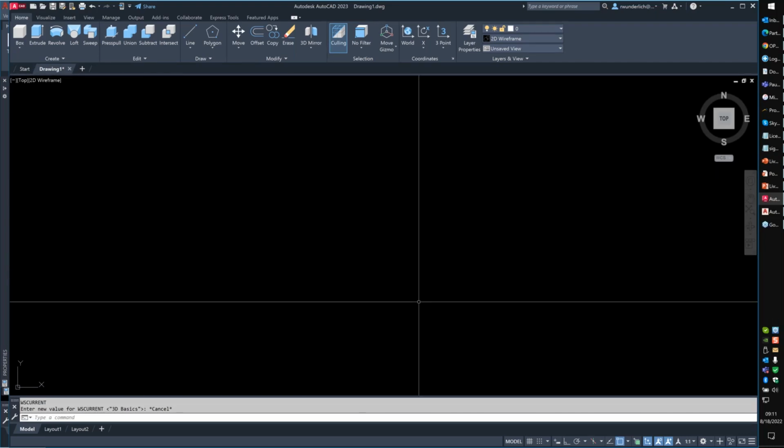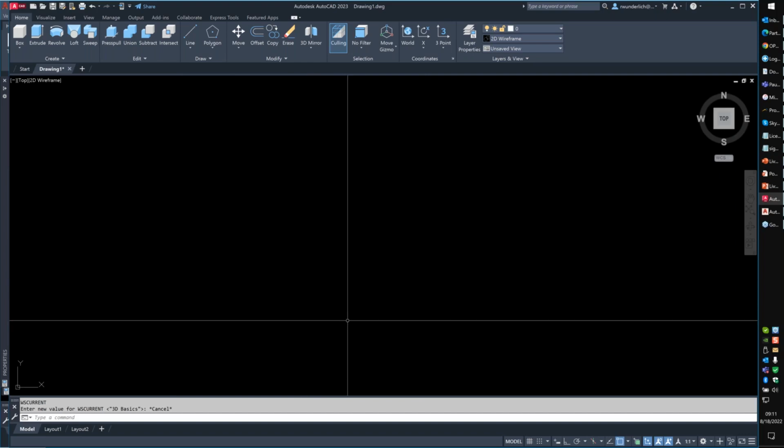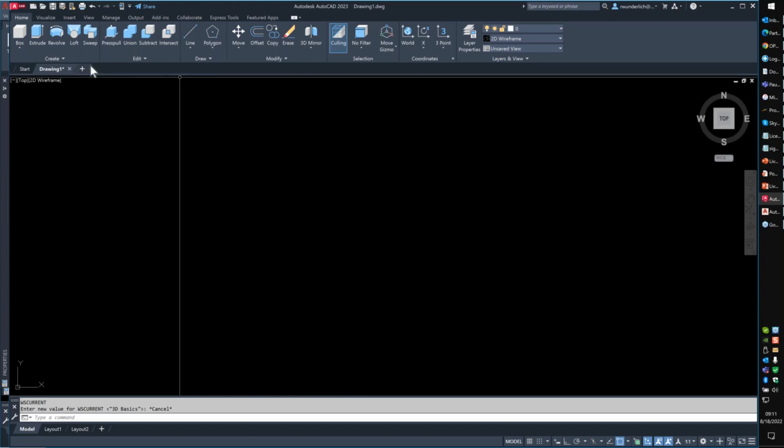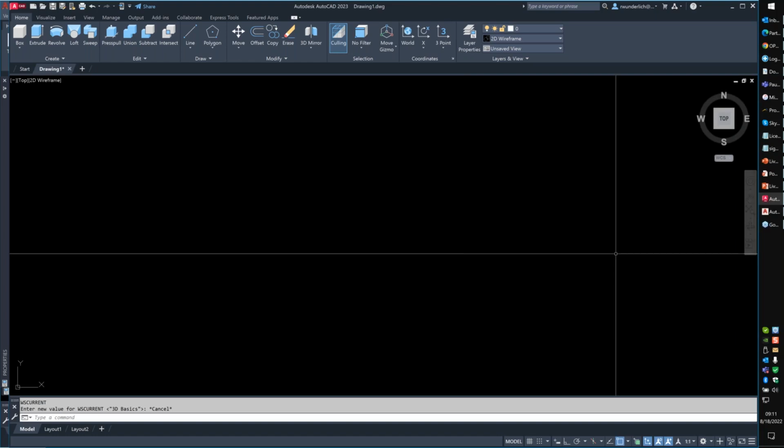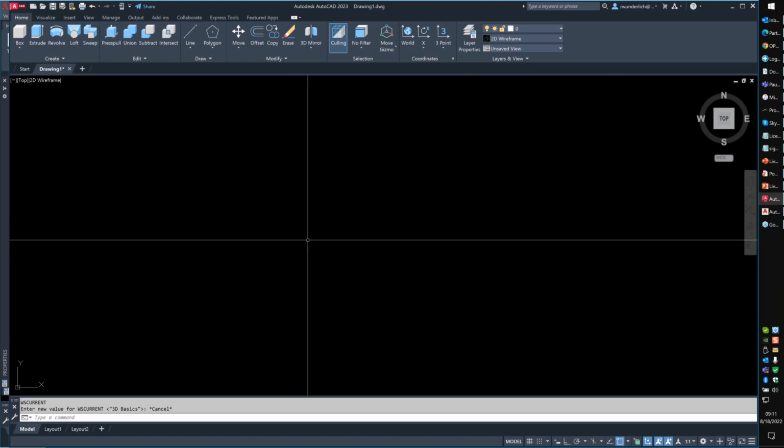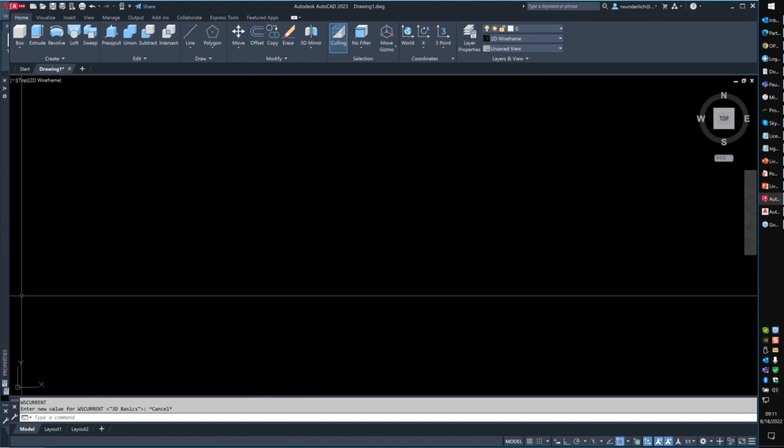I generally recommend building them in all profiles. The reason why is that whether or not the toolbar is on or off is generally stored in your profile .aws file. It's not generally stored in the registry. So when you make these changes, it's important to make sure you change it for all your workspaces.